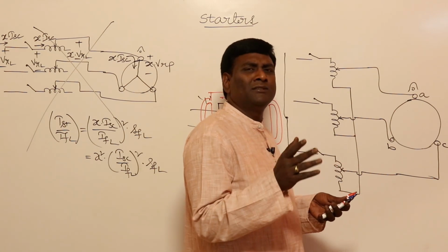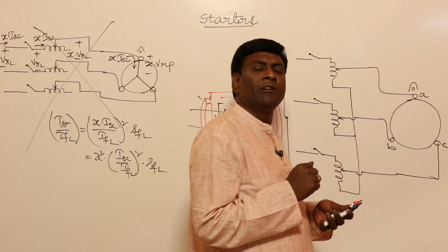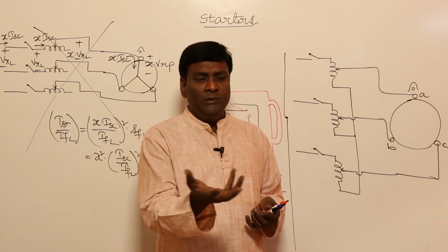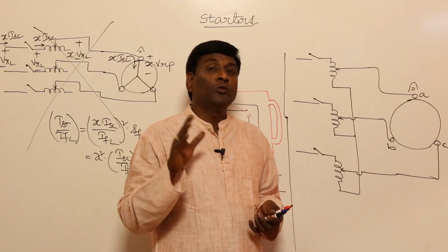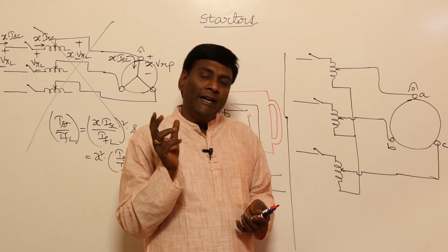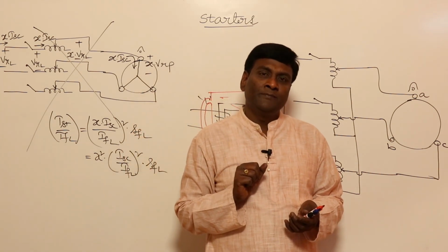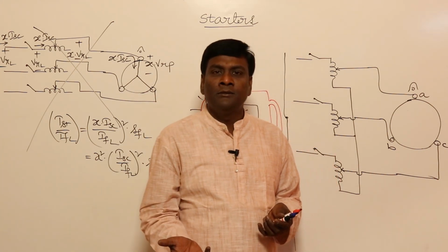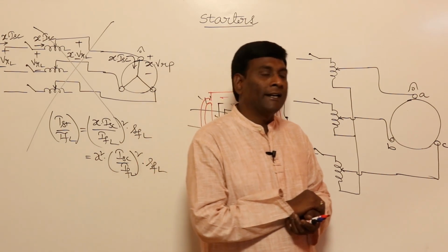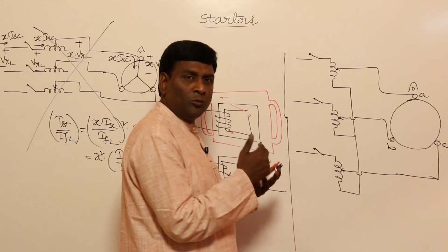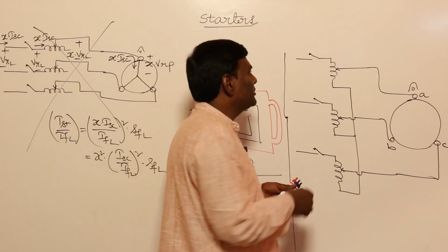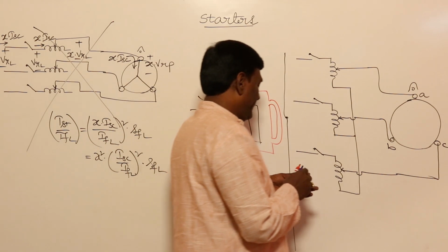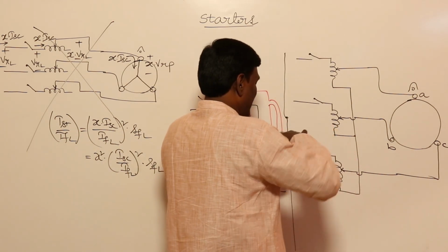High tension motors, we say HT motors. In interviews also, some interviewers will ask what is meant by HT motors. Normally 440 volts will be the three-phase supply available to consumers. For example, directly we can take at 5.5 kV, primary level distribution, so 5.5 kV motors will be there. Those motors are called HT motors or high tension motors. For high tension or high capacity motors we can use this, because the auto transformer will come in.